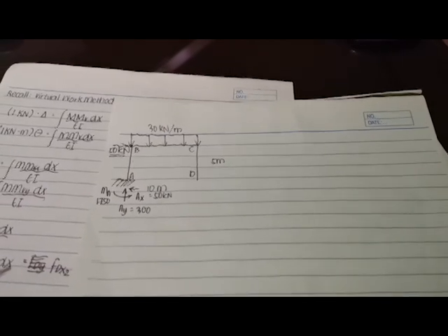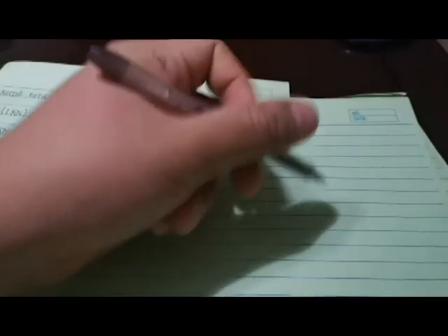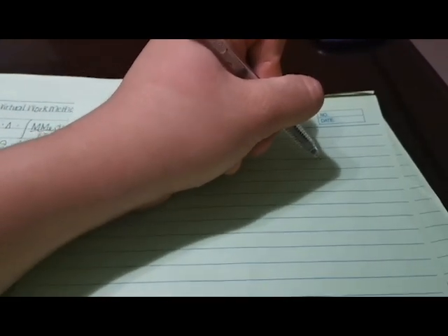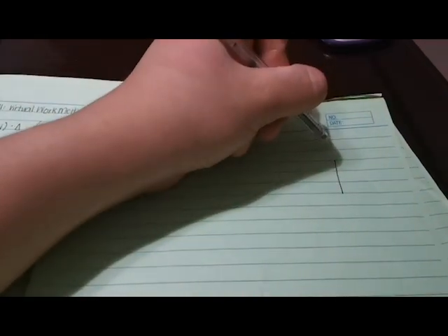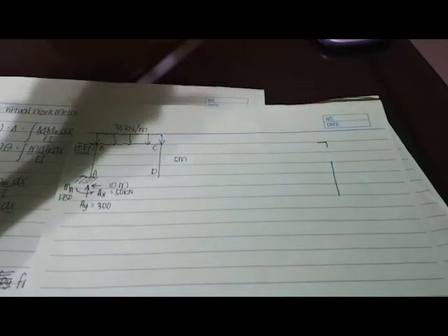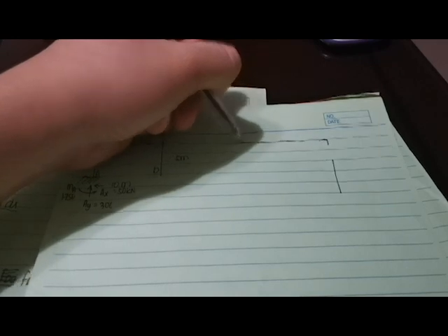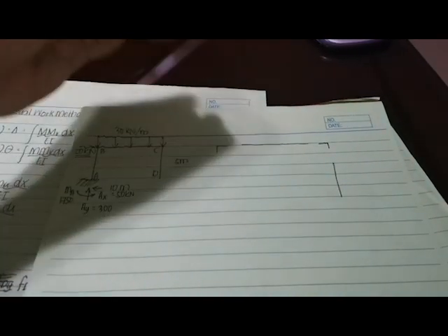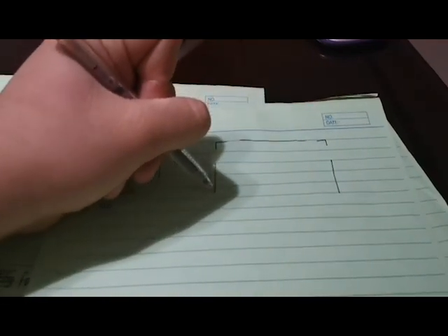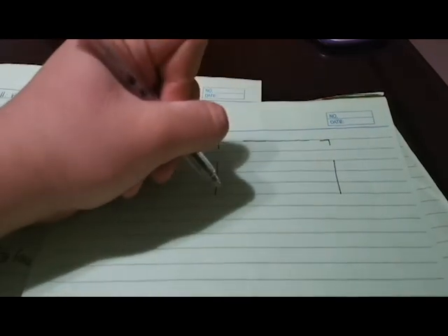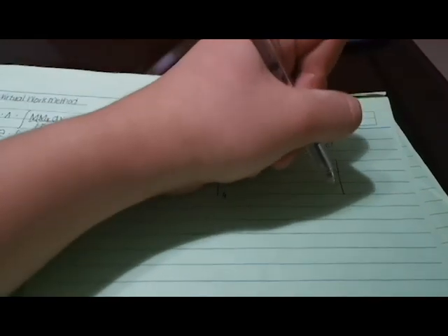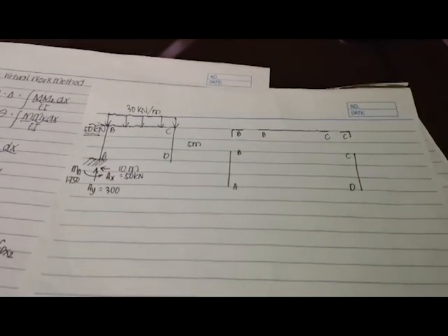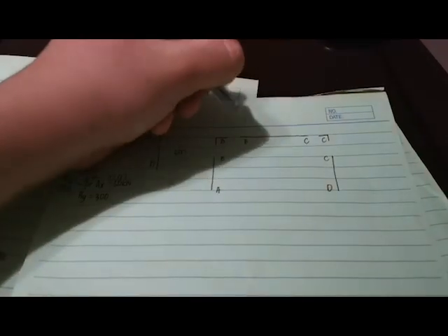So now we all have the reactions. We separate it member by member and joint by joint. So first we are going to isolate member CD and joint C. Then let's isolate BC and joint B. And then isolate member AB. So let this be your A, this is your B, B, this is your C, C, and this is also your D. So the technique for doing frame analysis is, let's put all the loads first.